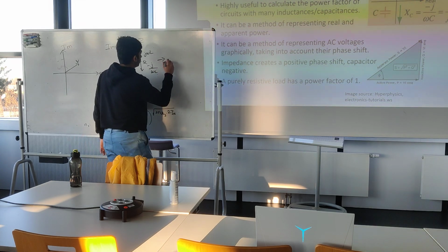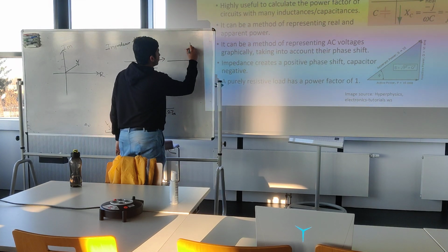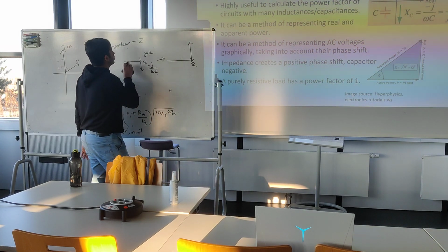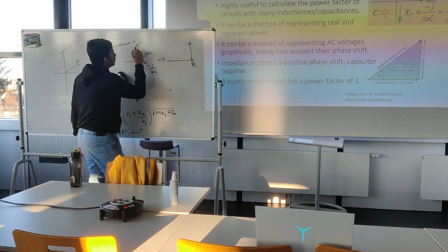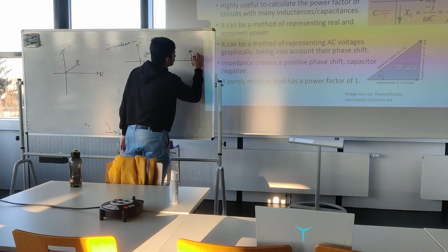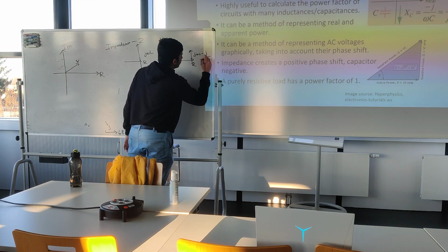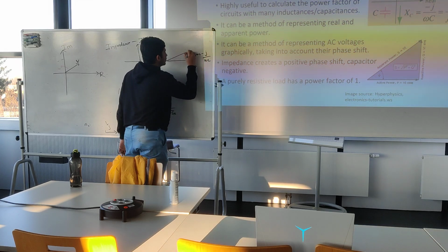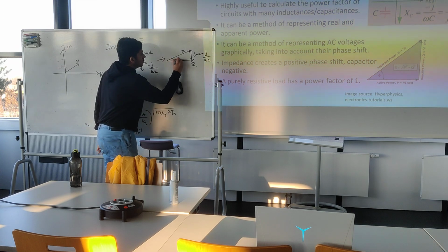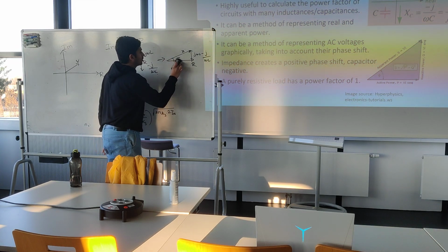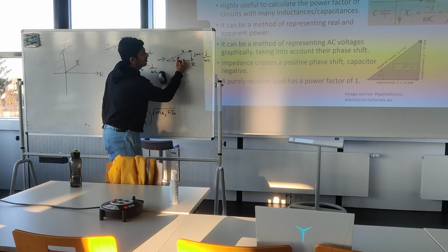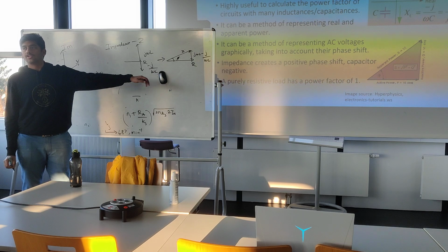So effectively what that gives is, you have the resistance, and let us say the inductance is dominating. j omega L minus j by omega C, and this is the effective impedance. And the angle we see here will be constant. This will be the phase shift phi, and you can use that to get power factor.